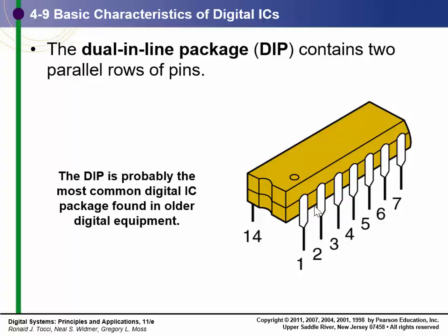When I say a dual layer board, it means that you've got circuits drawn on the top of the board and the bottom of the board. Nowadays, a 10 or 12 layer board is not uncommon, where you've got layers in between that connect the circuits. And then there's connections made between the various layers.